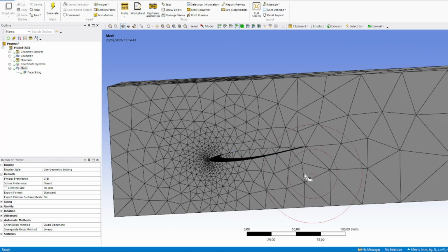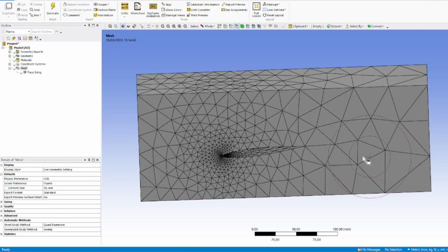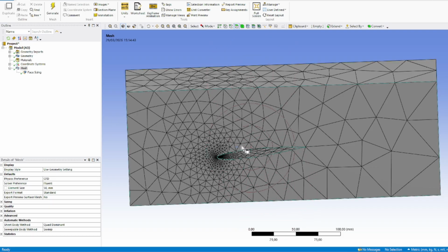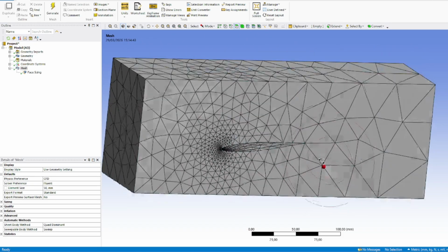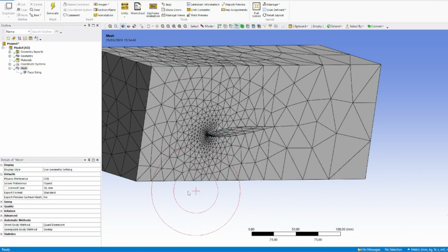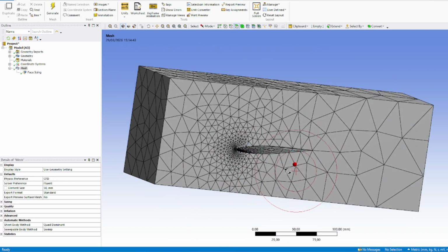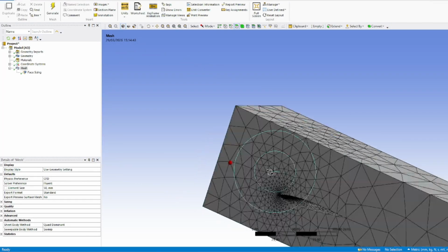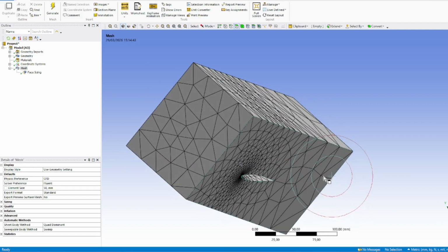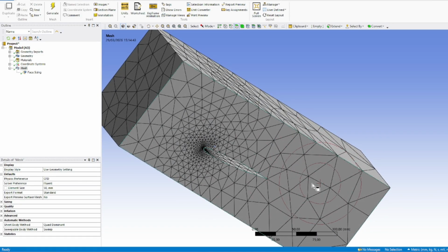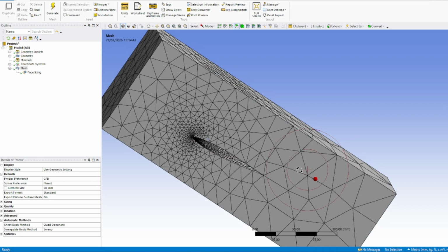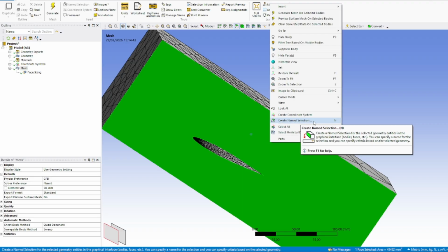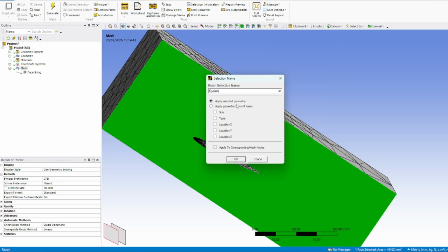Okay, maybe your model is smaller, or is an entire plane, for example. So maybe you cannot select all the faces of your model. But with the last option, it should be great. Now, once we have our mesh finished, we are going to select all the faces that we are going to program on the setup, for our wind or for our solids. So we first click the symmetry face, right click, and create named section. We call it symmetry.